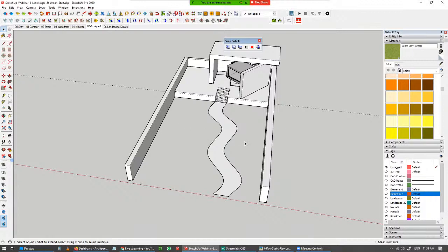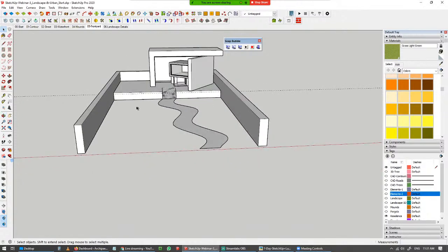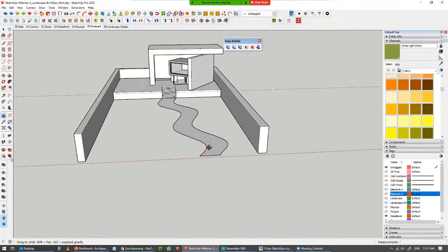Next, we will create much more complex mounds, but the extension or the process here is much simpler. Here we have a meandering pathway leading to this building. Now we want some kind of sloping mounds coming down from both the boundary walls, connecting to the edge of these pathways. For that we need to define the edges of the pathways on either side.